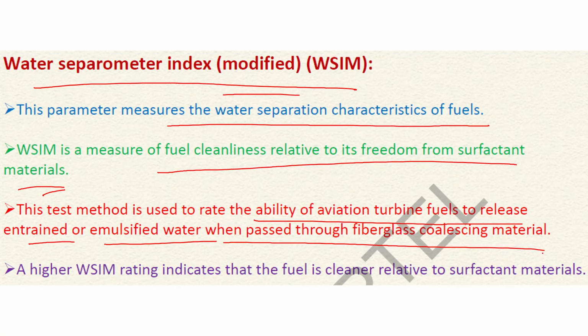So if we pass this aviation turbine fluid through this fiberglass coalescing material, and the emulsified water coalesces easily, then it has a good water separometer index.